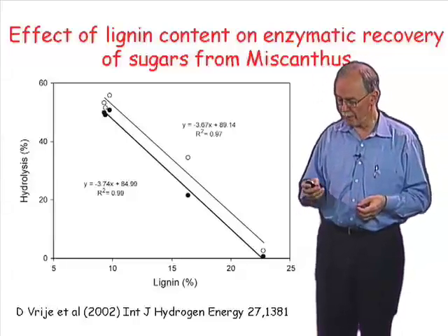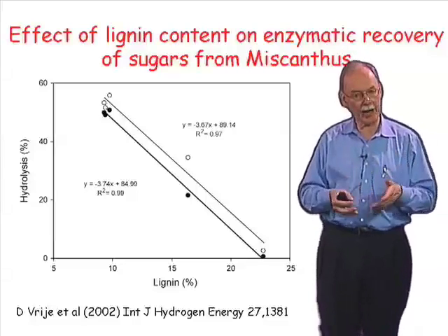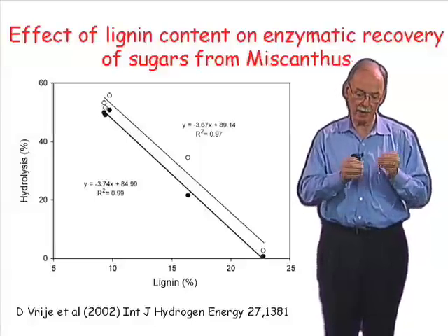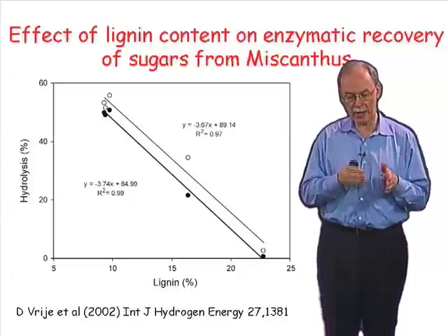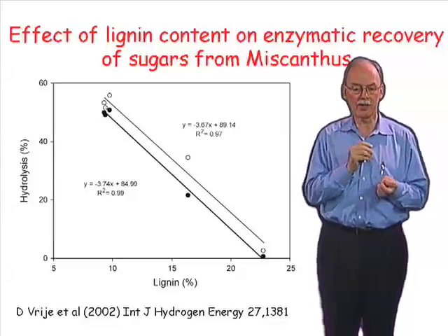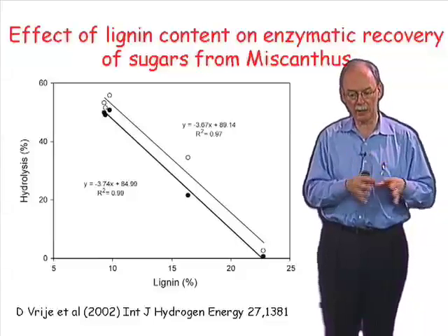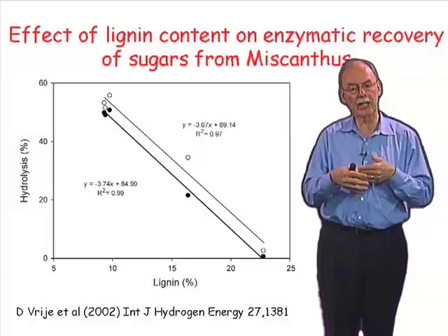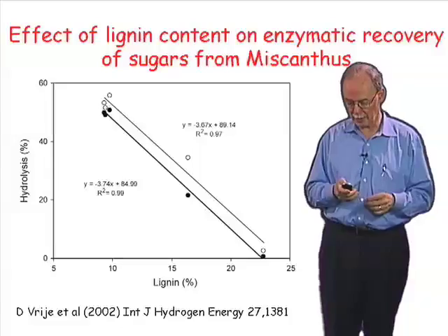So one of the things then that the pretreatment that I mentioned earlier, the boiling in hot acid or related kinds of treatments, what we think that does is that first of all, it disrupts hydrogen bonding, causes things to loosen up, and secondly, it causes sort of non-specific hydrolysis of the hemicellulose. So the hemicellulose sugars start diffusing away, and the linkages to lignin start getting broken. So everything starts to loosen up, and the enzymes can penetrate.